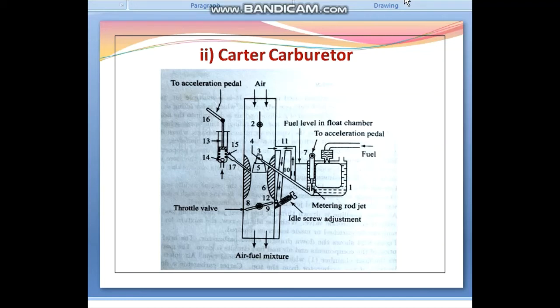The mixture from venturi number 3 flows centrally through the second venturi, that is number 5, where it is surrounded by an air stream, and finally goes to the third main venturi, that is number 6, where fresh air surrounds the stream from venturi 5.